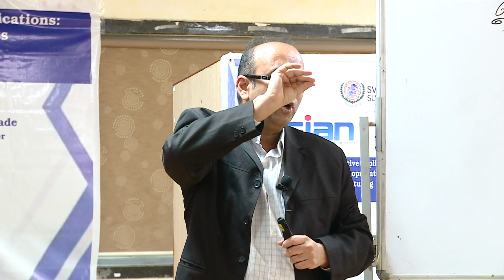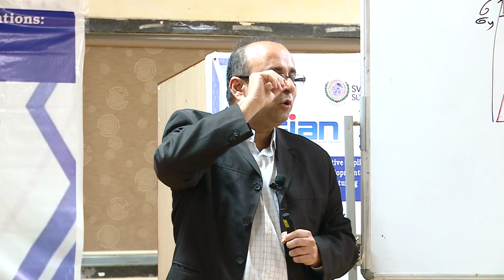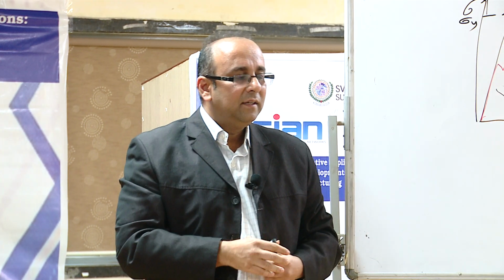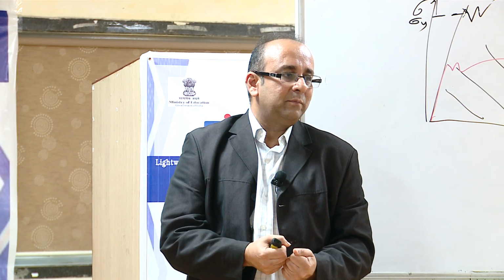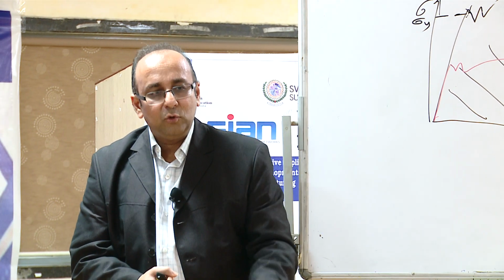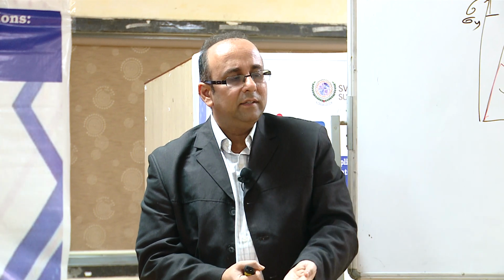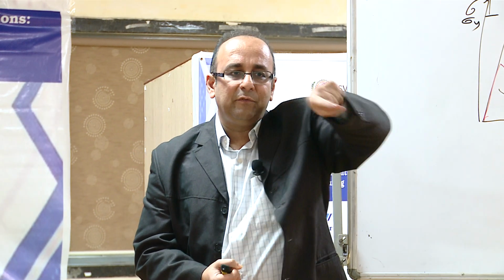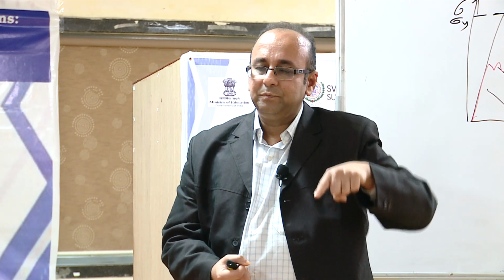Practically your spot welding tool will break. Even if your spot welding tool is very robust, the part will break because you are giving so much high clamping force. Plus additionally, if you are hitting the part in the welding zone and cooling it, we are creating a local heat affected zone. It means there is always a chance of cracking in that area.